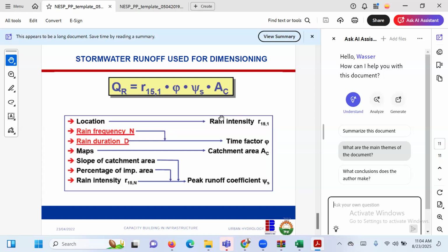And when you see something like this, rain intensity, arrow 15, 1, what does it mean? It simply means 15 here means the duration is 15 minutes and the return period is 1. So that's like normal base design. We usually use 10 minutes or 15 minutes to estimate our runoff. That's to say, the first 15 minutes of a rainfall will determine whether there will be flooding or not. I've said it severally. This is how these predictions are done.